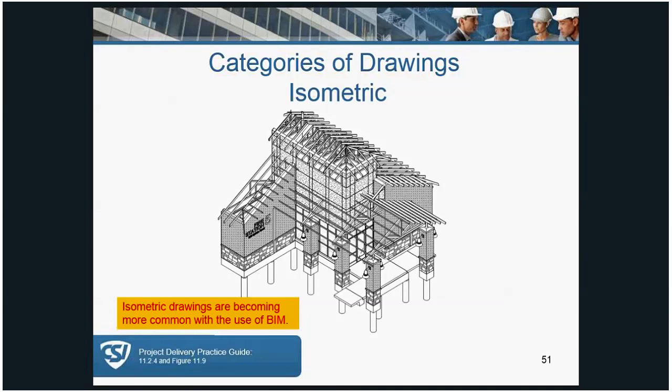Isometrics, for instance, are very useful in detecting conflicts and resolving conflict resolution. Some contractors develop BIM models of interstitial spaces above ceilings to ensure the ductwork doesn't conflict with the structure, the fire sprinklers, and the lights.